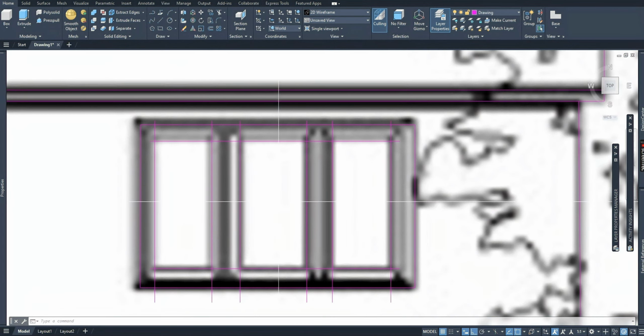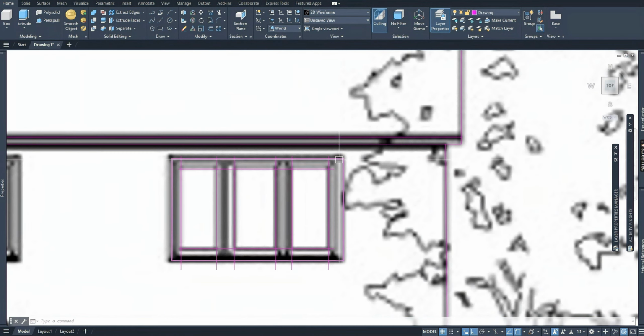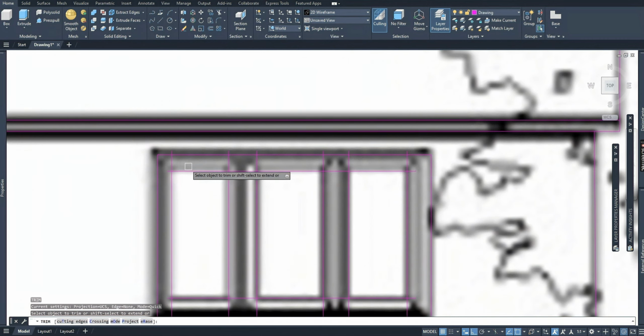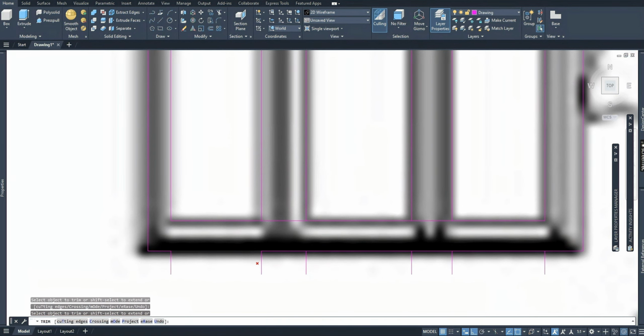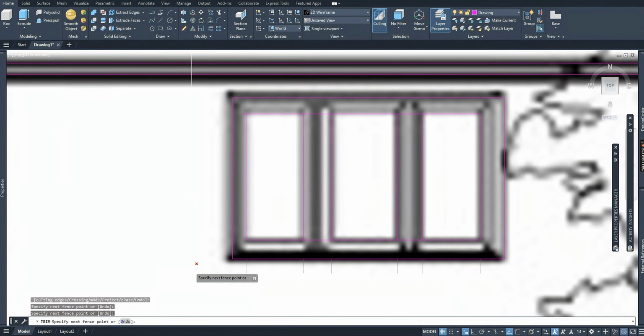And for example, even with this whole drawing, you see how I just left the lines rough, instead of trying to find the exact measurement where it lines up to a reference drawing. I can just create it rough, and now I can just use the trim command, TR on my keyboard, and left click the option. Now I can just go through, left click my mouse and drag it. Anything the line comes in contact with will just get rid of. So it's a much quicker way of working, rather than having to be perfect the first time around, and I just come back and edit it as needed.